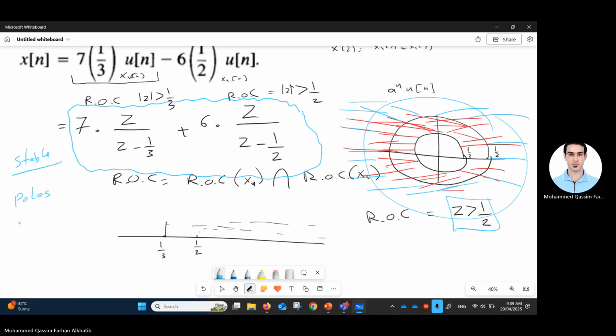The poles should be inside, any idea? The unit circle. So basically you draw the Z plane, and the poles we symbolize by X's. If they are somewhere inside the unit circle, then it is stable. If they are outside the unit circle, then it is not stable.